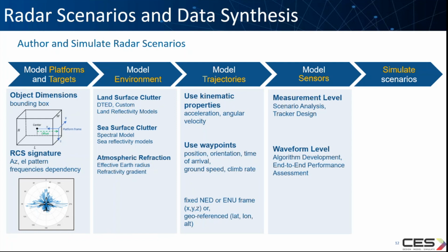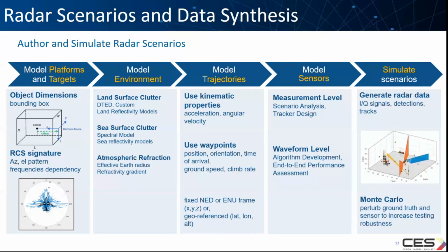Sensors can be modeled, or a radar sensor can be modeled, at different levels, as I mentioned. For such a scenario, we verify or design radar at the measurement level using scenario analysis and tracking design. We can also design at a much more detailed level, which is the waveform level, and that will include DSP algorithms, end-to-end performance assessment, and so on.